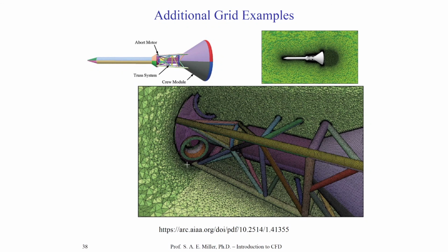It's a lot of fun, so you can inspect your mesh quality. If you do this, then you can see the surface grid. For example, all this surface grid is the colors. Then you can, of course, see the advancing front method near the wall of the vehicle. Remember, the advancing front method worked in 3D across all surfaces shown here. We're only examining the advancing front method in 3 dimensions with these particular cuts of the plane for visualization.